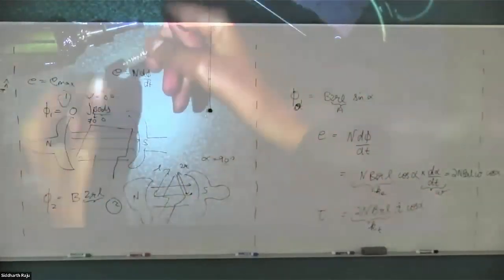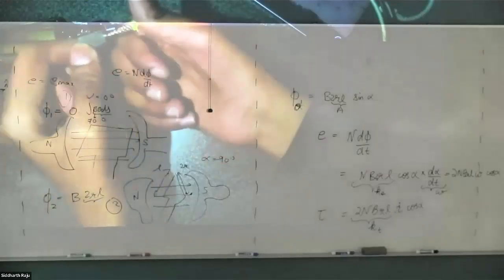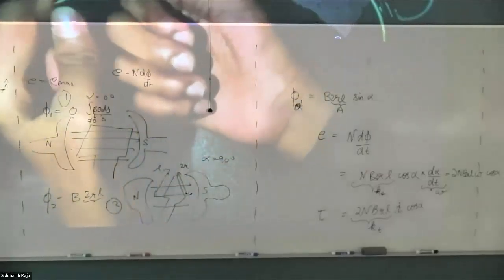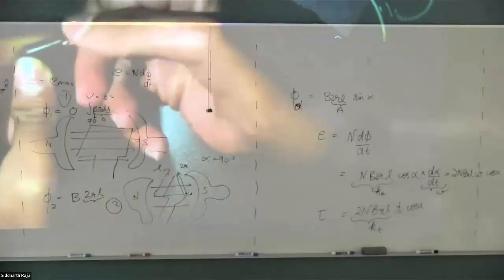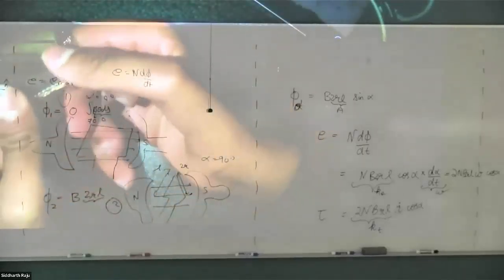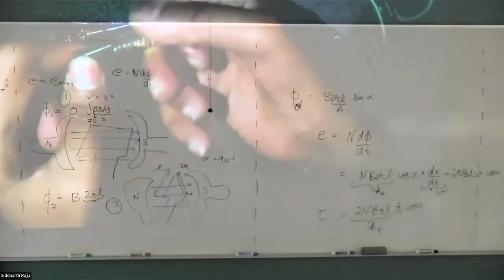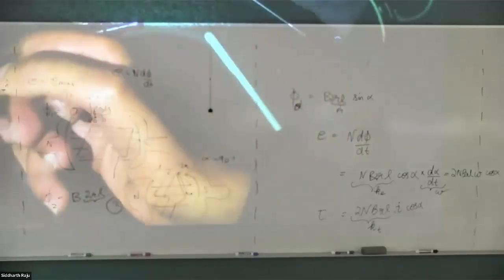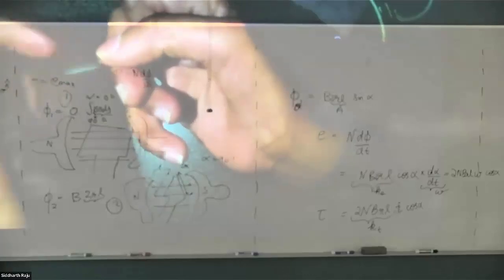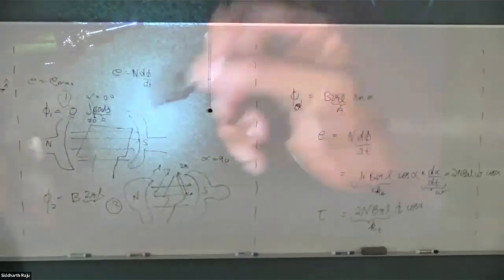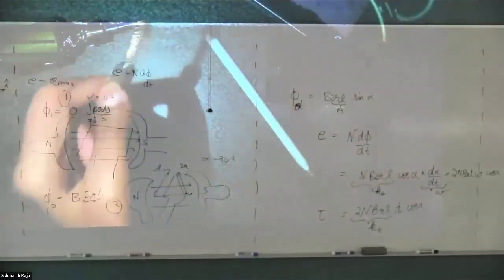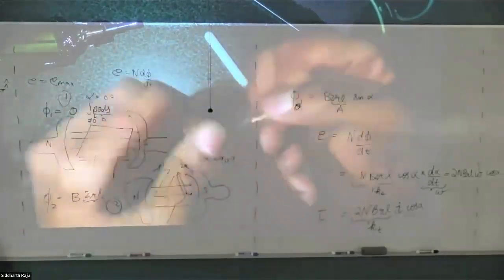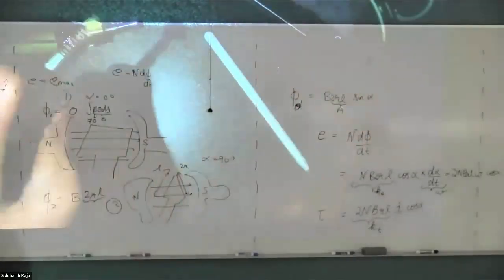What happens is that over time this brush starts to wear out. The spring will keep on pushing it so that even if the brush wears out, it can still make contact. But it's only up to some point. If it wears out too much, then there is no amount of spring that can make continuous contact. It's going to get to a very small length, and you'll have to replace it. And typical DC motors in industries like train locomotives, some old trains still use them.